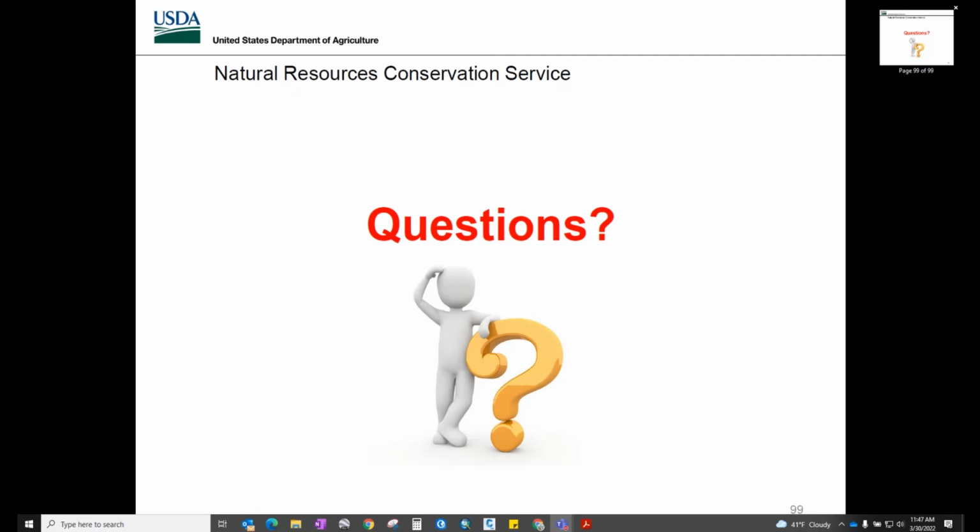No. So creating those points, great question. I've done stakeout ever since I had a total station when we were using 5,000, and you can do it with GPS as long as you localize it. So if you did an original survey that was based off of 5,000, there's ways to localize your survey and use GPS and localize that survey based off of that 5,000 location, believe it or not. But no, the answer to your question, yes, you can use stakeout for total station, GPS, anything electronic, robotics.